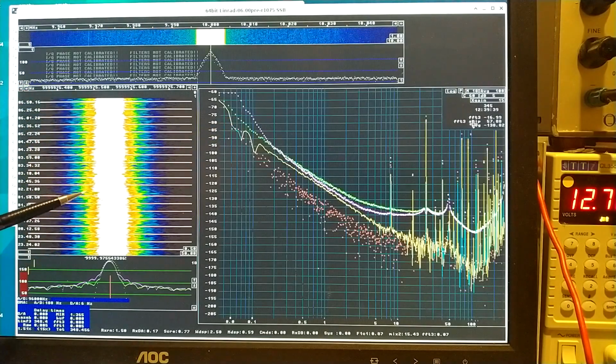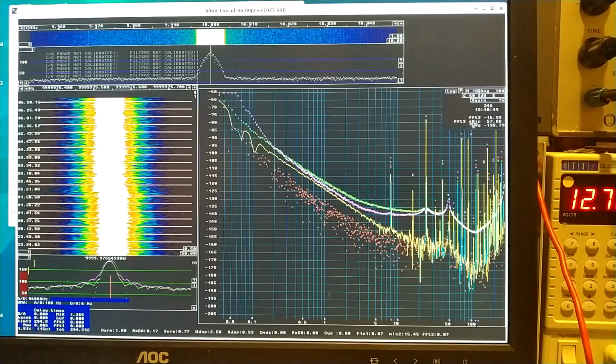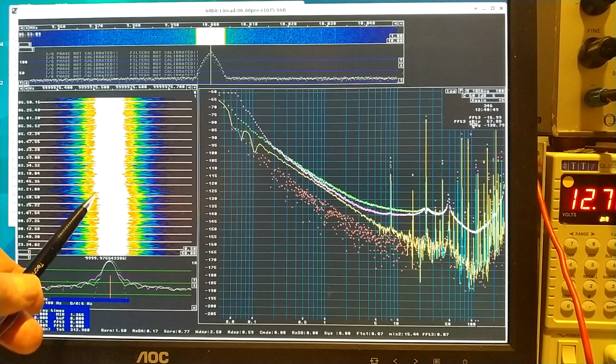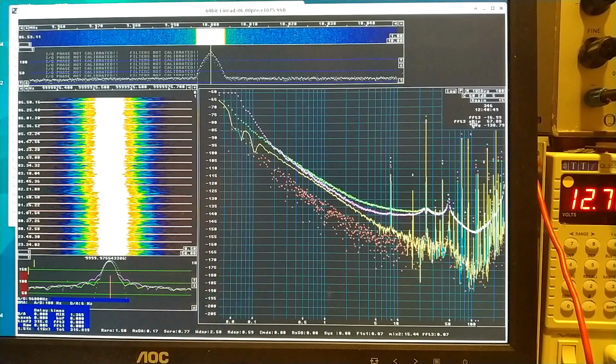This has been running for 12 hours and 40 minutes. And I can see here, at about 2 o'clock in the morning, UTC, the frequency made a jump. And I think that is the explanation to the peculiar flat noise I saw in the first measurement. And for this measurement, the Linrad stop collecting data when there is a big transient seems to have worked to not include the data where this jump was in the buffers.